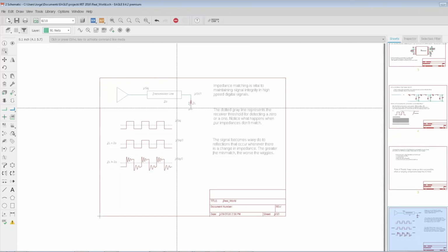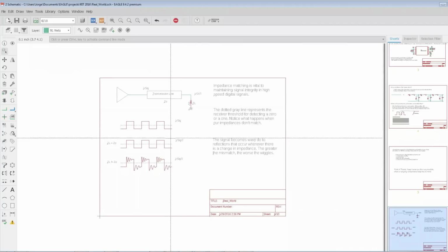Now, obviously, you can't always avoid vias. And in future webinars, we'll analyze what you can do to make the via safer, to make the via as transparent as possible to the signal. Those are things that have to be really taken into account with high-speed boards, where now you have different materials, different things that you have to deal with. Okay, so that's what we would keep in mind here. Maintain the thickness of your traces. In doing so, you maintain a constant impedance, and you can get cleaner signals.